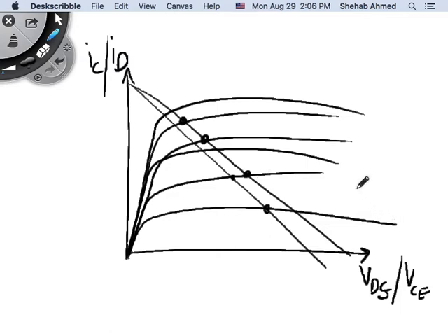No, this is a BJT. You're controlling the base current. If it's a MOSFET, you're controlling the gate voltage. Remember? With different base currents or different base voltages, you were choosing to operate the device at a certain characteristic, and then based on the components that you put around the device, you were defining your load line.